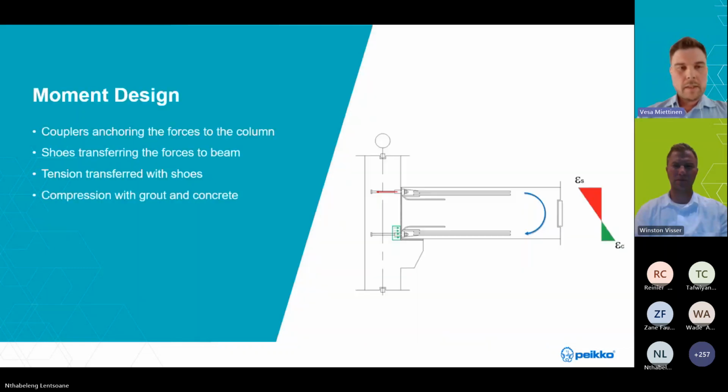All right, then a few words about connection design. Firstly, if you think about the moment design, you have some forces that you need to transfer from the beam to the column through these connection items. So here you can see the shoes. You place the shoes, in this case, in the top and bottom. You lap splice it with your beam reinforcement.